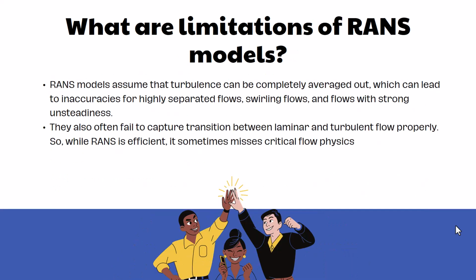The next question is, what are the limitations of the RANS model? As I said earlier, the RANS model assumes the turbulence and averages it out. So it can cause some inaccuracies when we have to analyze highly separating flows, or where we want to resolve the eddies, or in particular how the flow separation is happening. In some particular cases it will fail to capture the problem. Hence RANS is efficient for general purposes, but whenever there are specific requirements, then we use the LES model.